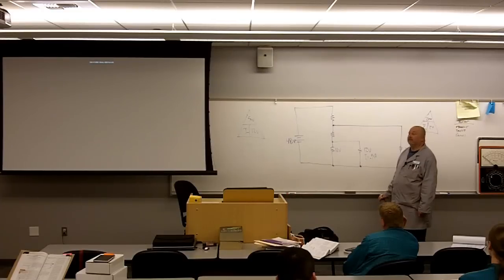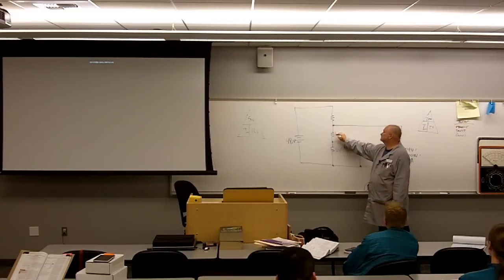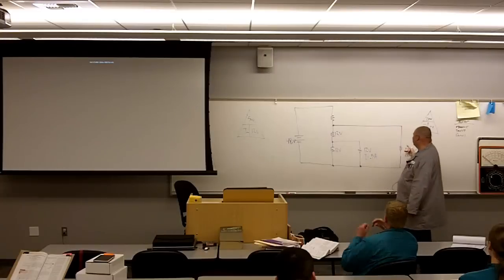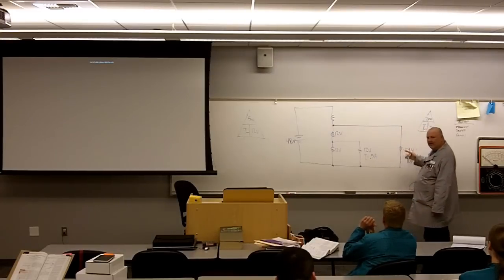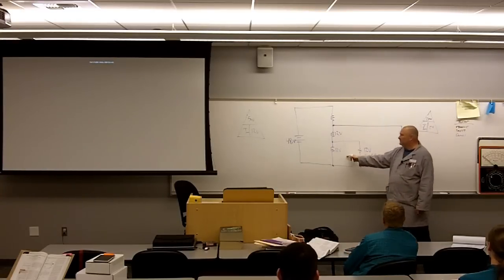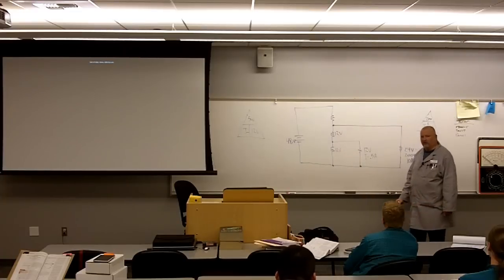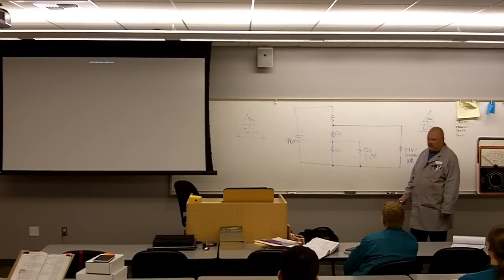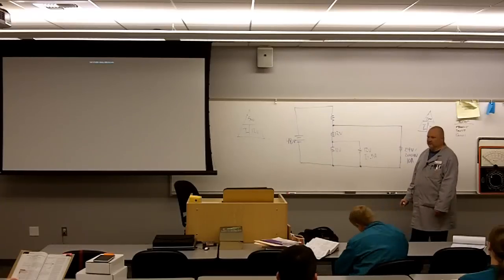Why 12? Because it's double this, 12 volts. Yeah, and I am connecting this radar unit in parallel. I love it when you talk that way. Parallel with these two resistors that are in a voltage divider network. Okay, so what we did is we just built a voltage divider, a loaded voltage divider.